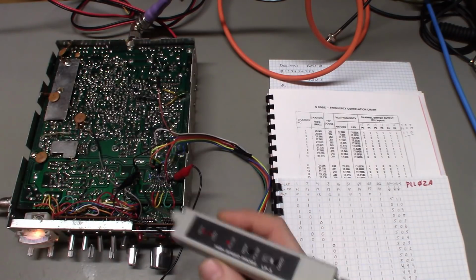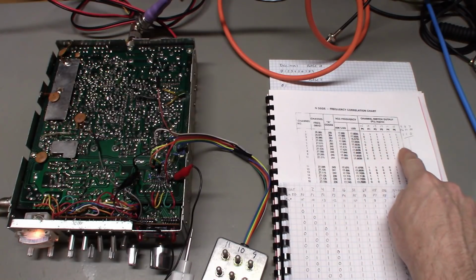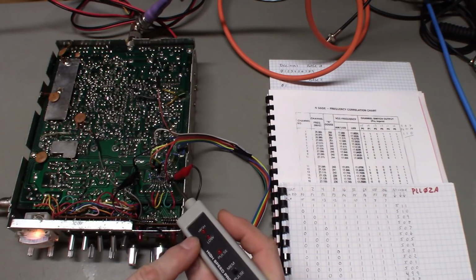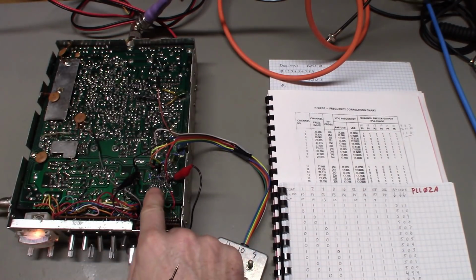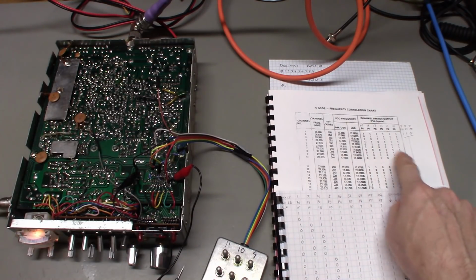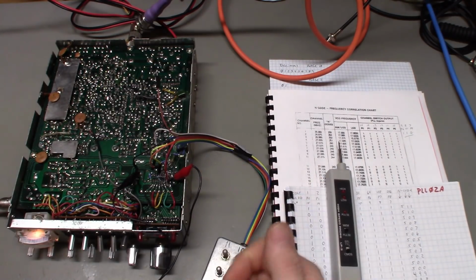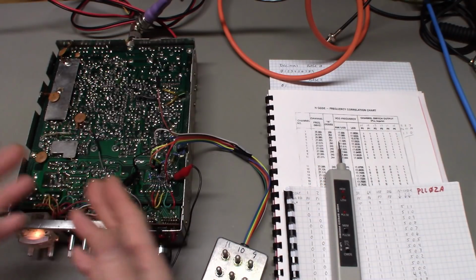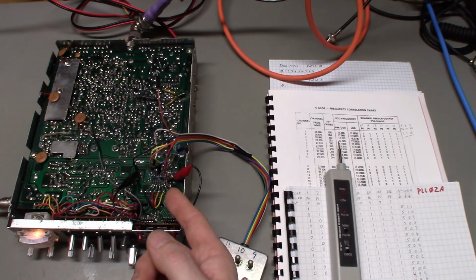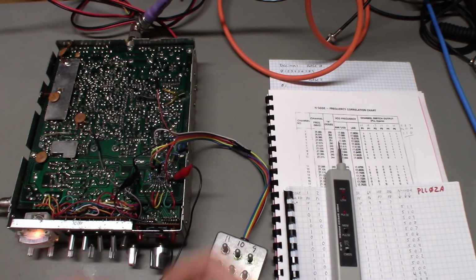With this, you could troubleshoot that. You could put the radio on whatever channel, look in your service manual, see what the programming is supposed to be getting to the PLL, actually test it down at the circuit board and see if it's the same. If what you're testing at the pins of the PLL matches the truth chart, and the channels still aren't right, you either have frequency synthesis problems, like a crystal, somebody may have done a channel modification, they may have put a different crystal in the radio, could be a bad PLL chip, but you diagnose from there. But you would have confirmed that your channel selector is okay.